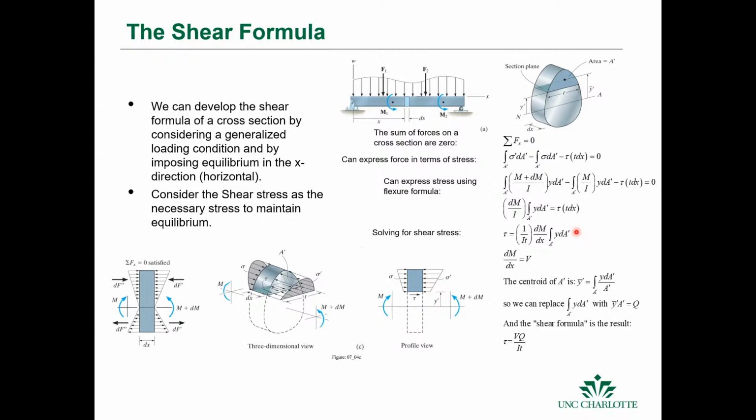And what we do is we simplify this equation, and we take this integral of y dA, and say, well, if we know the distance to the centroid of that plane, that would be this distance from the neutral axis to the centroid of the area above which you're trying to calculate the shear on that plane, we call that Q. And then this becomes the shear formula.